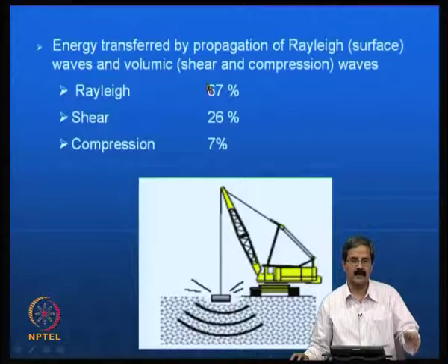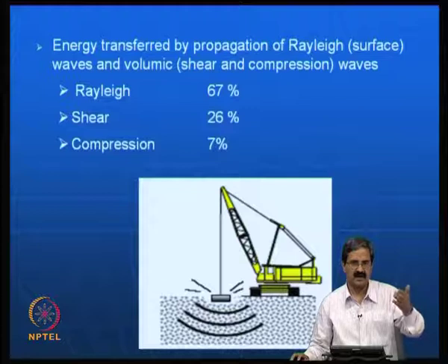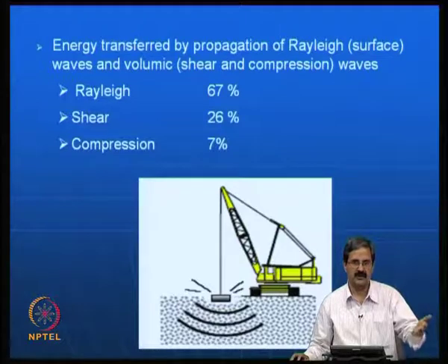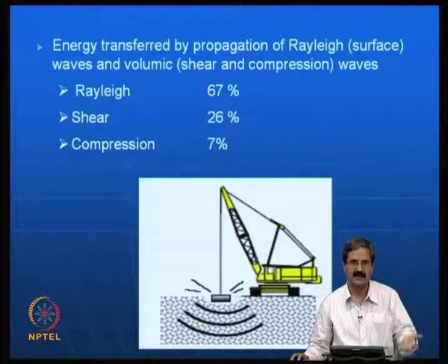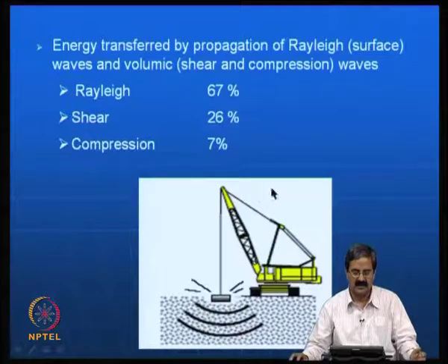The important thing that we should understand here is that you are trying to transfer some amount of high energy, like the kinetic energy is converted into a potential energy, which means that the kinetic energy which you can calculate upon tamping gets introduced into the soil system, and since this energy is imparted to the soil, it becomes more dense, it becomes stronger, that is what it means. So, this is a relative contribution of different types of waves here.